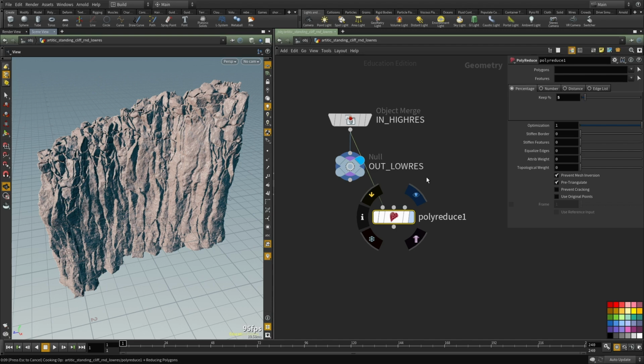And this is a very, very interesting node. Now, it has a little bit of limitation in terms of attributes that are not going to be inherited properly and things like that. But hopefully they'll be improving this in the next few releases. For now, we're just going to be using it to generate low-res meshes and use them for preview and or for real-time rendering. So I'm waiting for this node. It's going 40 seconds. And again, we're dealing with the 4 million points. So this is perfectly fine in terms of the time it takes to give us back a proper mesh.